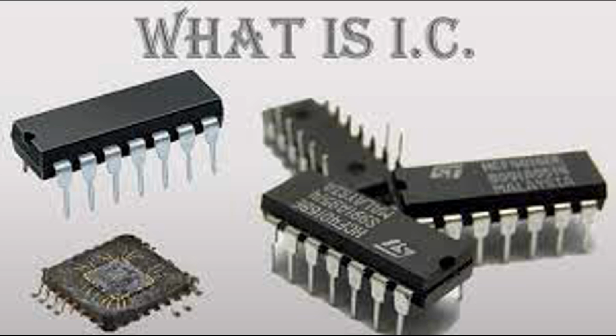On-chip components. Microcontrollers typically include a CPU core for executing instructions, program memory, flash or ROM, for storing the program code, data memory, RAM, for temporary data storage, input-output, I/O, pins to connect to external devices, peripherals like timers, UART, PWM, and ADC for interfacing with the external world. Often a clock oscillator and reset circuitry.